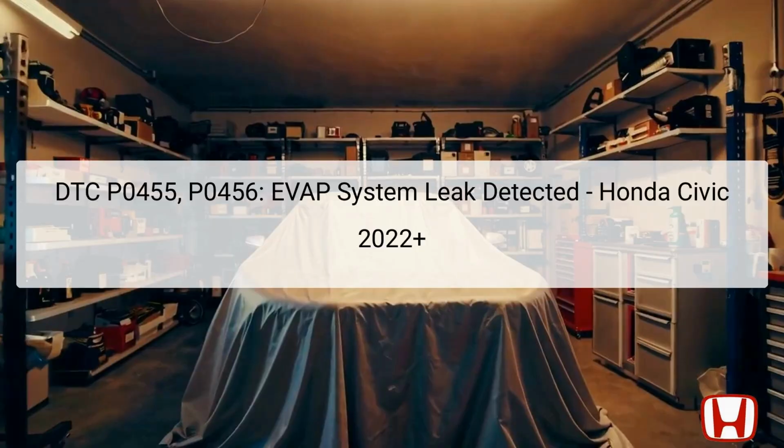The diagnostic trouble codes DTC P0455 and P0456 refer to issues detected within the Evaporative Emission (EVAP) system of the Honda Civic 2022 and newer models. DTC P0455 indicates a very large leak, while P0456 suggests a very small leak in the EVAP system.